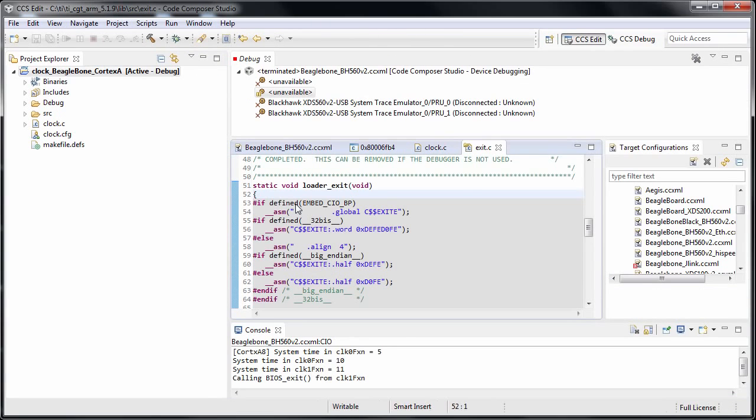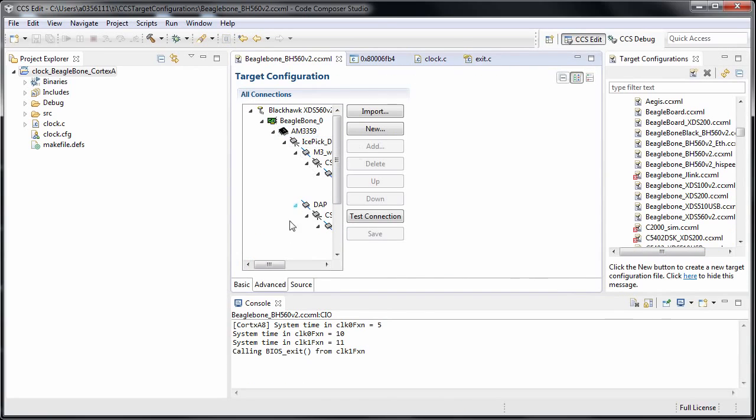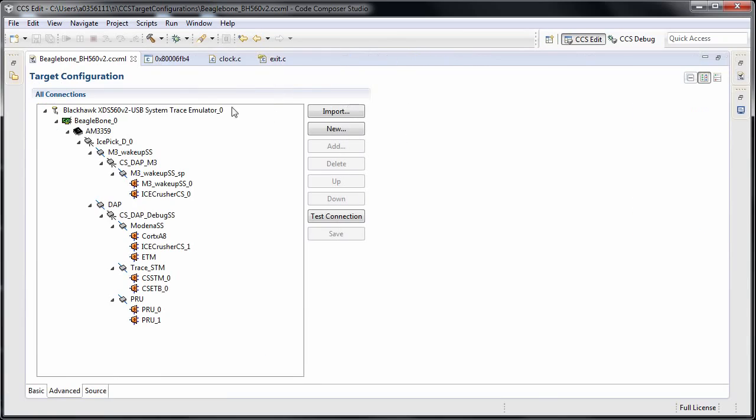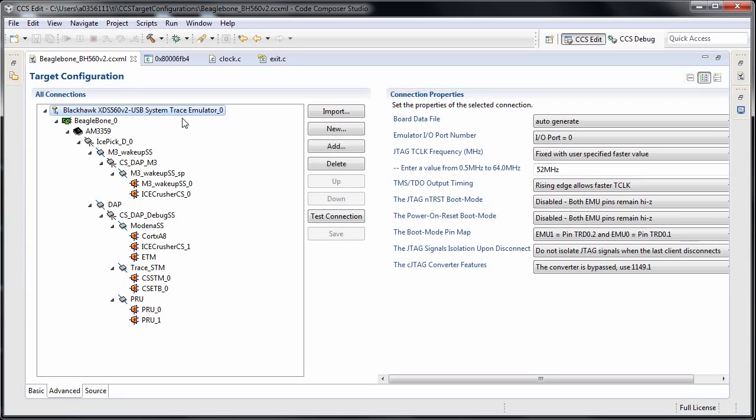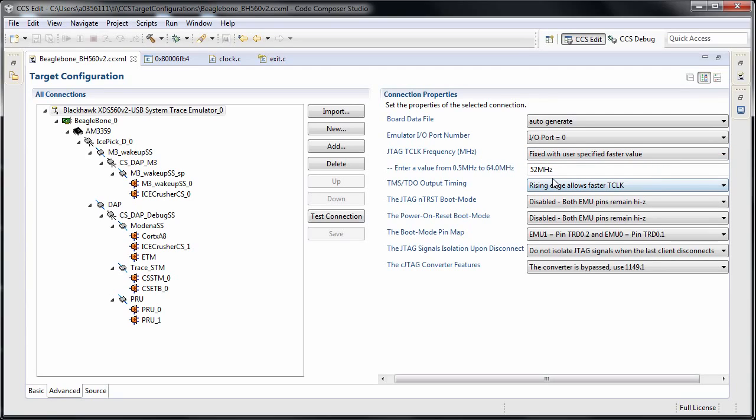So a few important closing comments regarding this iterative technique. Just recapping a little: always use the advanced configurations of your target configuration device. Always keep in mind that the configurations typically come with the default 10 megahertz. Always a good idea because it's the most reliable, especially if you're doing your own board. The other thing is it's always trial and error experimentation with the fixed value.